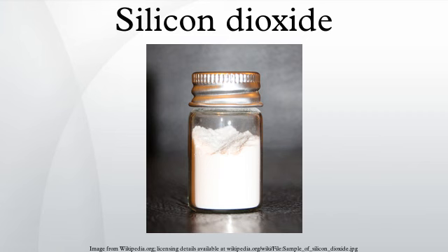Fused quartz. When molten silicon dioxide SiO2 is rapidly cooled, it does not crystallize but solidifies as a glass. The geometry of the silicon and oxygen centers in glass is similar to that in quartz and most other crystalline forms of the same composition, that is, silicon is surrounded by a regular tetrahedra of oxygen centers. The difference between the glass and the crystalline forms arises from the connectivity of these tetrahedral units.